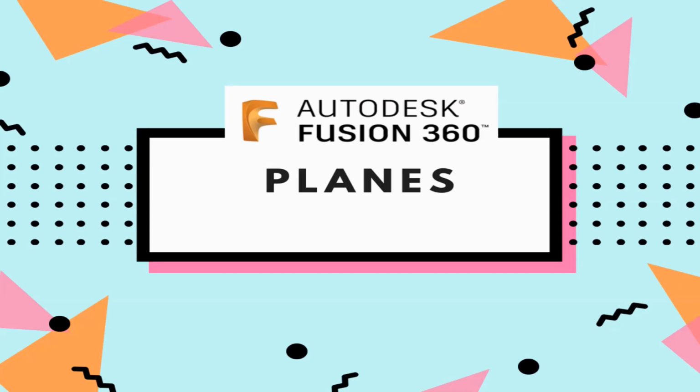By now we have understood that we need a sketching plane to first start our sketch for constructing any product. Currently we have selected the existing planes like XY, YZ and ZX planes, or we have chosen a face which has already been constructed. But we can also construct planes at desired levels so that we can create complicated objects.